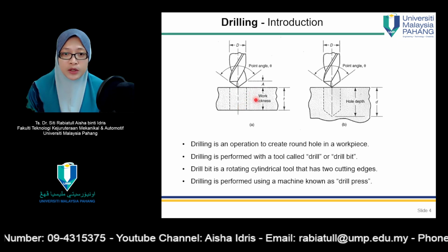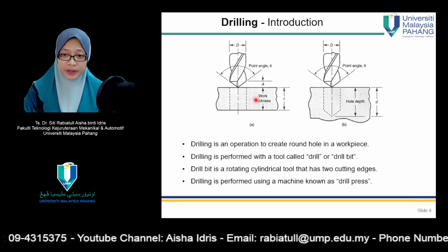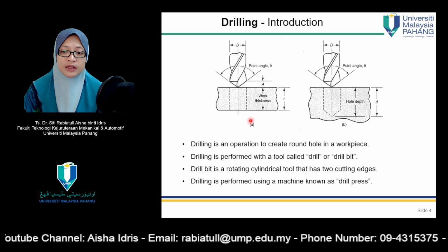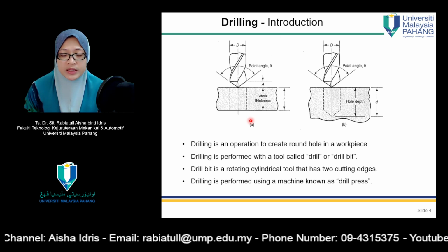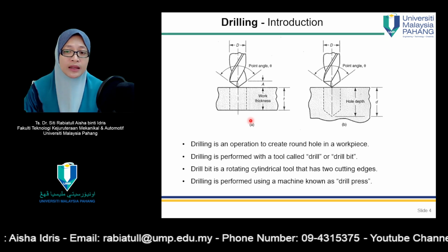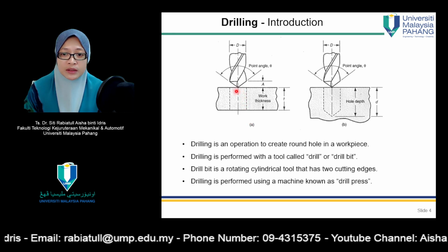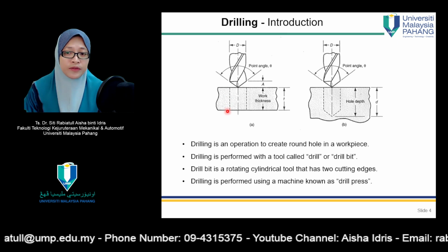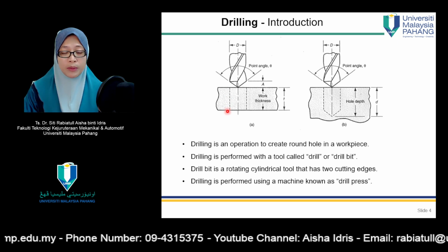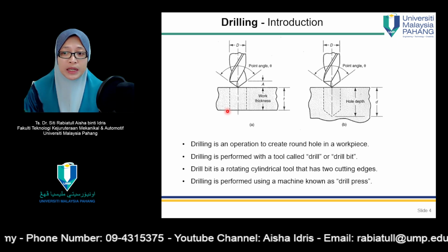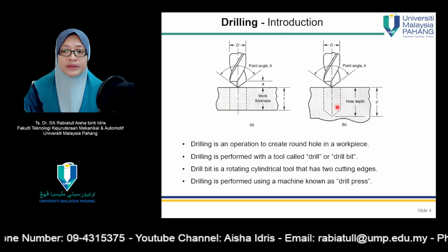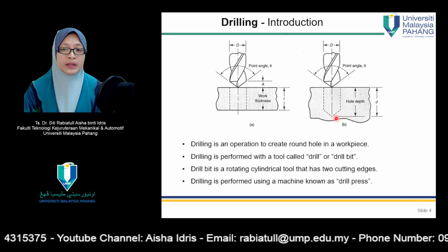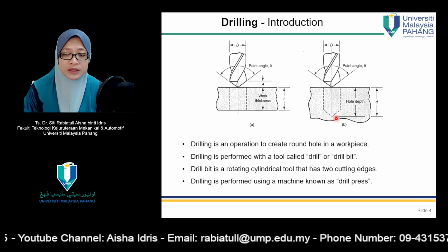on a workpiece using a machine which is known as a drill press, and its cutting tool is called a drill bit. So in drilling, we can either drill until it reaches the end of the thickness of our workpiece, and we can also do drilling by creating a hole for a certain depth of thickness only, which means that we do not create a through hole for our workpiece.